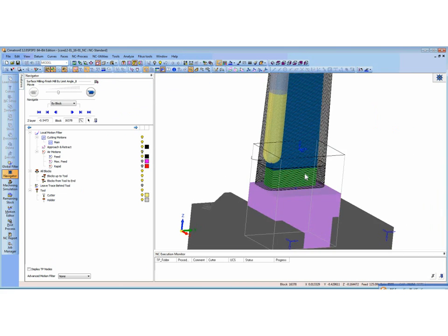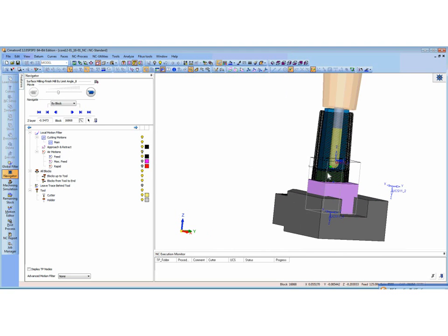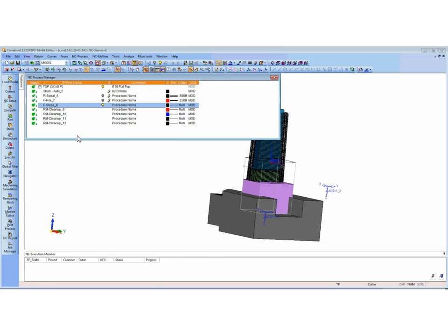So here we can kind of see by the darker color that the longer tool comes in at this point, and it has a lesser down step, slower feed rate, slower RPM, but it's all handled by the software. It just takes longer tools, whatever necessary, and it's only going to do picking where picking is necessary. So you can see how the template is flexible. You either work with short electrodes, tall electrodes, whether it needs picking or doesn't need picking. It's a very flexible type of automated programming.